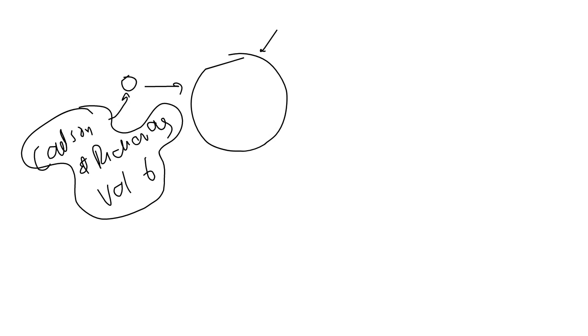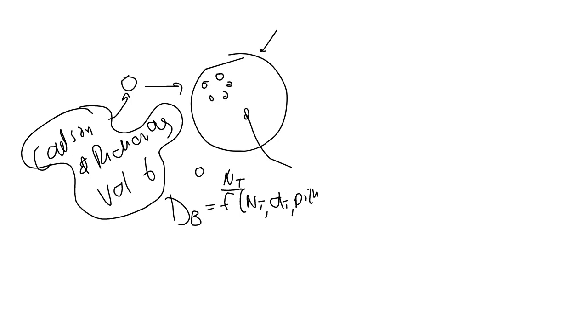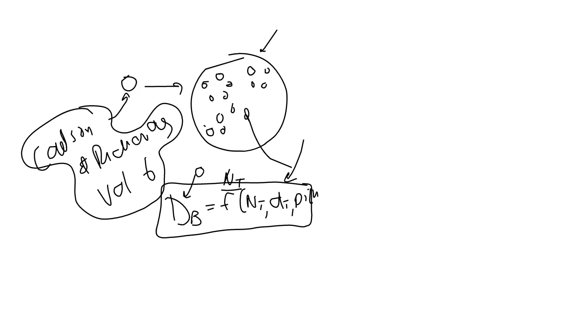Right. Okay. So in this tube bundle thing, what is important is that the number of tubes that you choose must fit in there. So there are no heuristics. It is a calculation. The tube bundle is an equation based on the number of tubes, the tube diameter, and your pitch. And pitch means, how do I want to arrange them? Do I want them like this, or in a square arrangement, or in a triangular arrangement? So how do I arrange the tubes? And then there are lots of equations. So you just plug it in and get the answer for your bundle diameter, on how to fit them in. Those are well-developed equations.